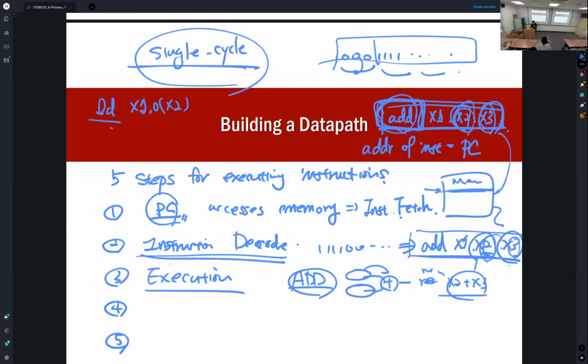The load instruction requires the memory, because with the computed address, the load instruction accesses memory. Some memory type instructions, such as load or store instructions, need to access memory. So this step is called the memory step.